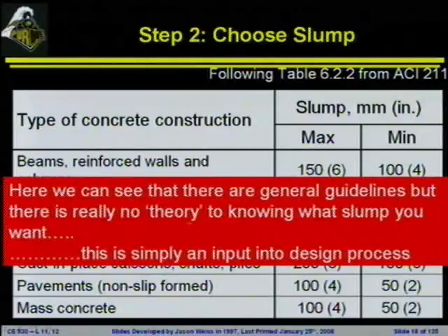I will provide you with this statement, even though I guarantee that someone will want to ask me a question about this later. There is no theory behind what slump you want. You have to make an assumption based on where the concrete is going, what type of equipment is going to be used to place it, and how stiff you want the concrete. It's simply an input right now in the design process.